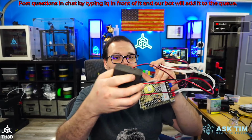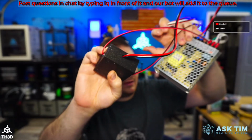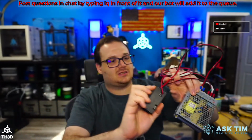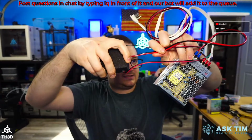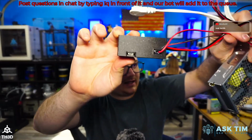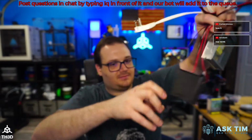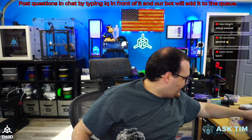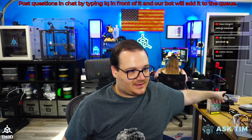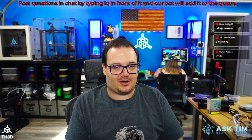You can see here I've got crimp ferrules on the wires going to the screw terminals, and for strain relief I actually just put a knot in the wire so you can't pull it out. Nice and simple. And then I've also got access to the micro USB port here if I need to plug this in and update it. And yeah, I've got rolls of strip lights sitting there, you can see them right there. So that's my latest project.